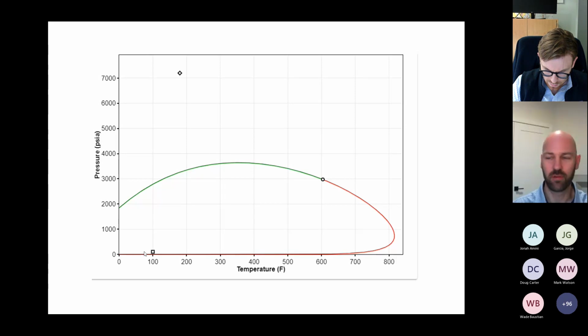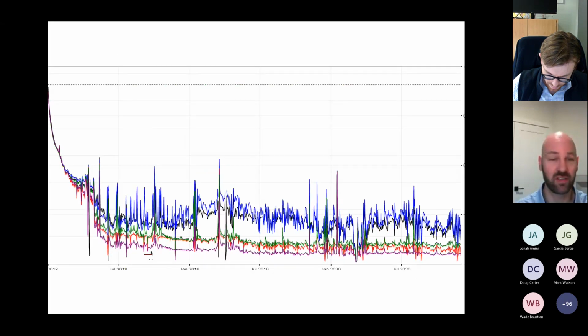The other thing is, in some other software, we're used to fluid property correlations being used to determine viscosity and compressibility. But in Whitson, we're using an equation of state model to give us more reliable bottom hole pressures in the wellbore, as well as everywhere else in the software. Pressure loss correlations: which one is right? In the past, you'd have to pick one and just hope for the best, but I really like that by default, Whitson is forcing you to see the entire range of possible bottom hole pressures from all the correlations, so you understand what that potential error is in your RTA work as well.